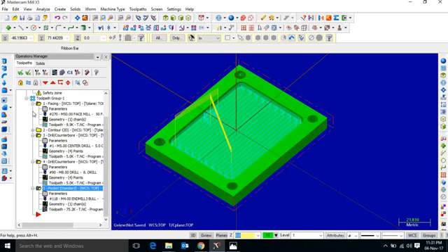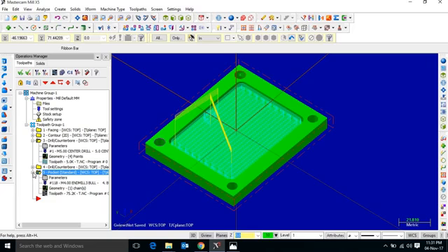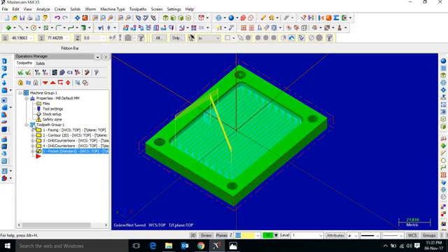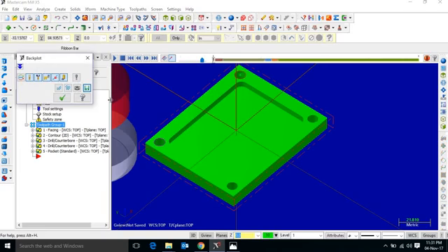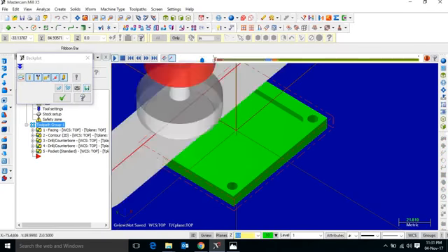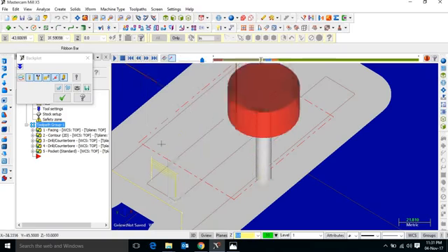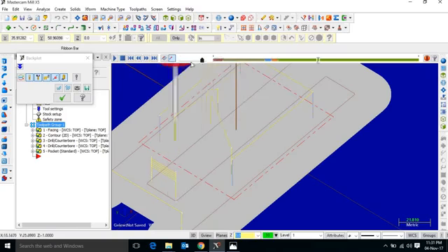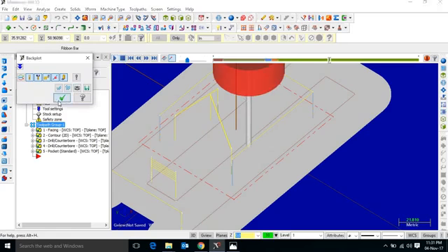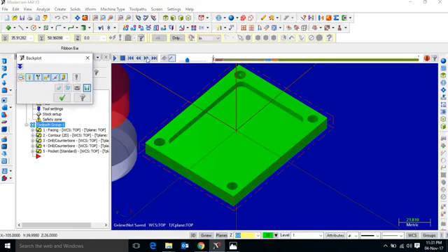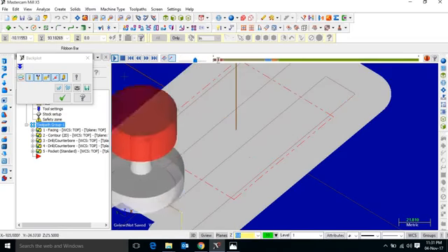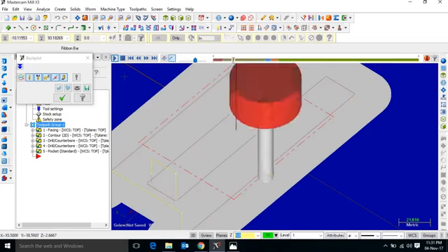So to minimize the operation, click on the minimize menu, select the toolpath, use the backplot and play. In this way the facing operation, the speed is too high. Stop. Okay, again we can see by reducing some speed. Play. In this way the facing operation is done.